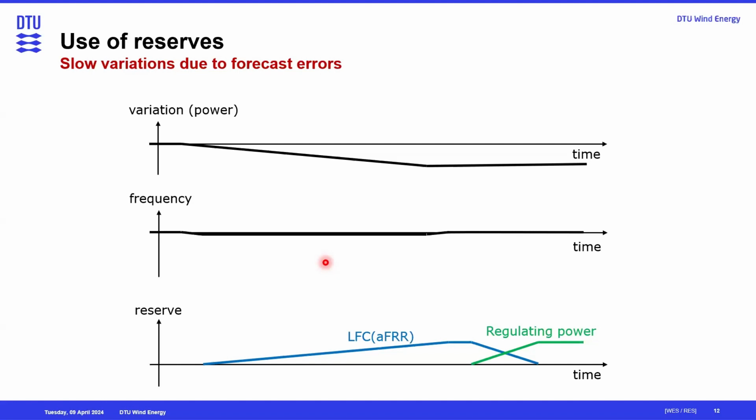So what do you do? Either you dimension separately what reserve you need for mitigating the forecast error, or you have strategic reserve or dynamic acquisition of reserves, or you ask the generators themselves to mitigate the forecast error by whatever way they have, instead of you, the system operator, being responsible for that. And there are different methods employed all around the world to do those things differently.